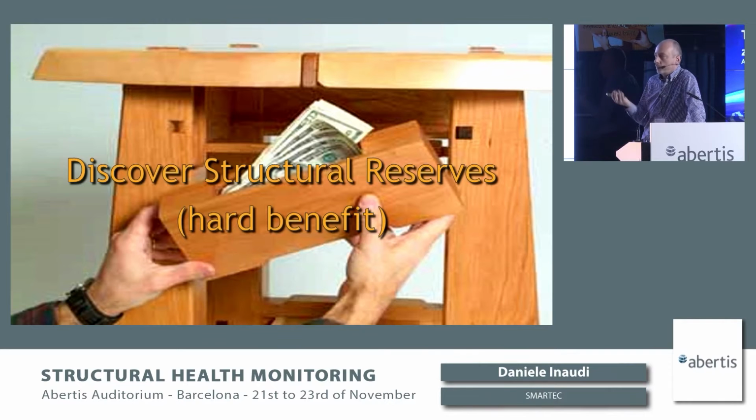And also there were some effects like rigidity in connections, etc., that were not really taken into account during the calculation. And so I will show you a couple of examples later on where it was safe to extend the lifetime of the structure without any major refurbishment or replacement of the structure.